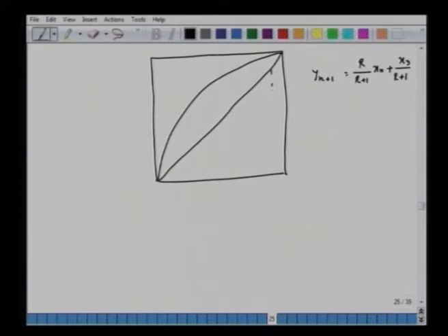This point Xt also satisfies the 45-degree line, which means at this point you can take a slope or intercept of Xt by R plus 1. We had this operating line. So with Xt equal to Yd substituted here, you get this 45-degree line.